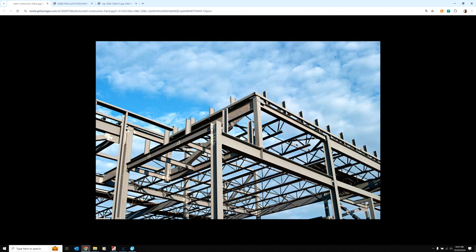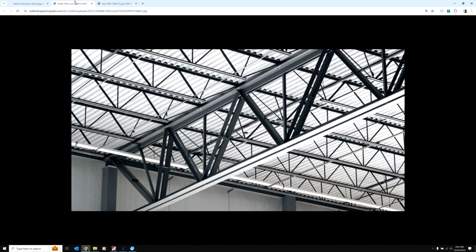This is an I-beam, solid structural member. Depending on the type of building, that could be an obstruction that we have to take into consideration when we're spacing our heads. The I-beam oftentimes means that we can't run a pipe as high as we wanted to, because we can very easily run through those open web bar joists and miss the fact there's an I-beam somewhere in the middle, and we ruin our whole plan. So this is an I-beam.